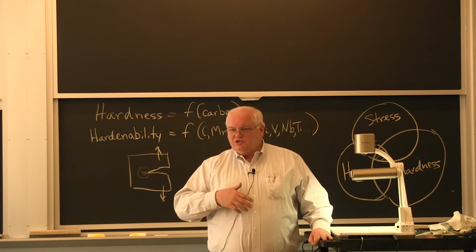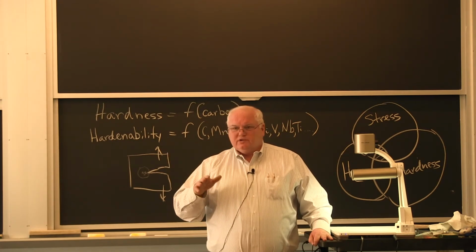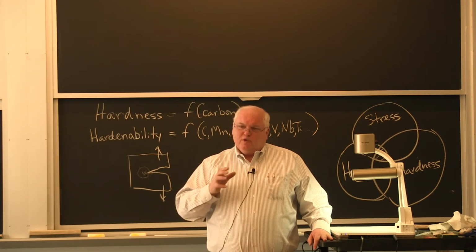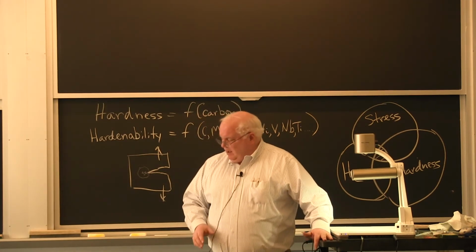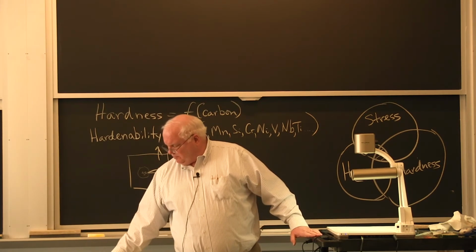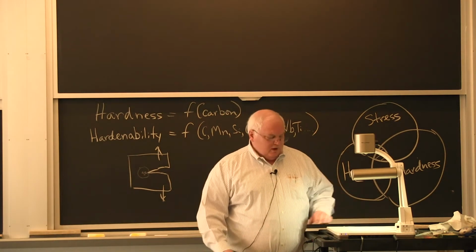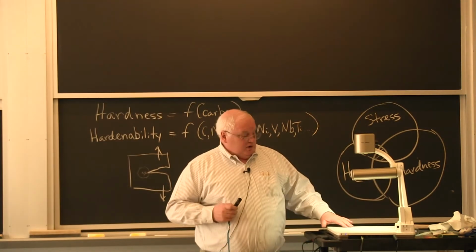And so, just to get some of their work done, they welded some of their structures. They ended up welding with austenitic electrodes before they finally learned how to do it successfully in the steels with ferritic weld metal of matching strength. The problem with the austenitics, you wouldn't get the same strength.